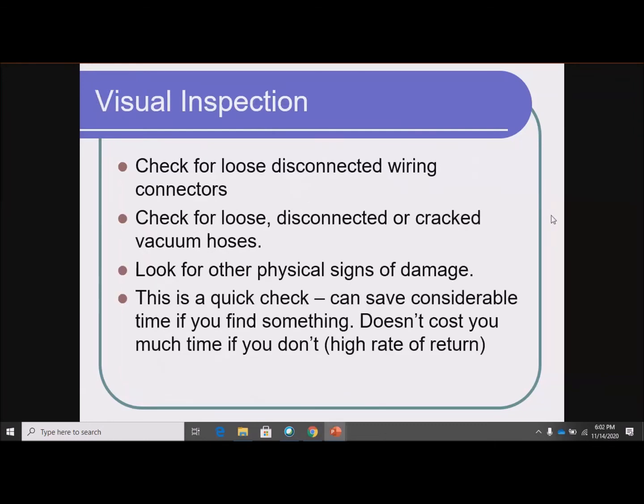So you may not be able to actually identify the system just by the symptom, right? And by the trouble code, but you may. What you're trying to do is narrow things down. You're starting with the entire vehicle. Between figuring out when the symptom occurs, are there codes, things like that, you're trying to narrow it down. You're trying to eliminate things that wouldn't be the problem.